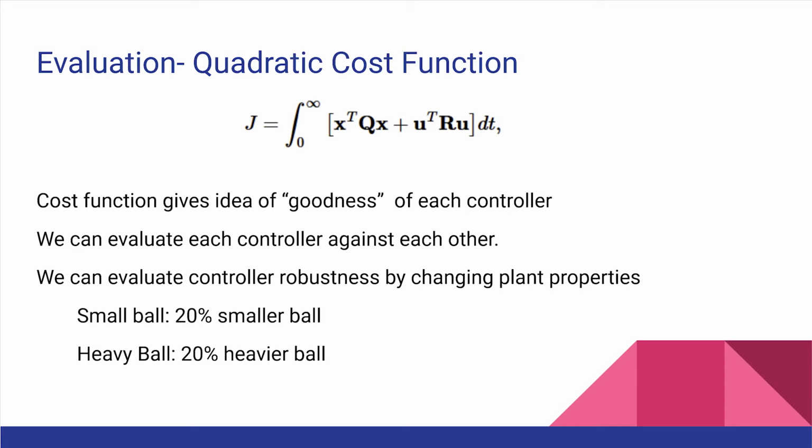To provide a fair comparison between each of our controllers, we used a cost function to compare their performance. Since one of our controllers was LQR, it seemed natural to borrow its cost function to evaluate the performance of the other controllers. By using the LQR controller as our benchmark, we tried to come up with a controller that could have a lower total cost. If we could find one, we'd have beaten LQR.